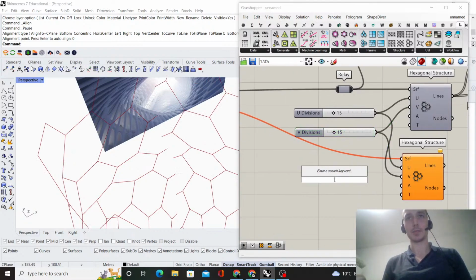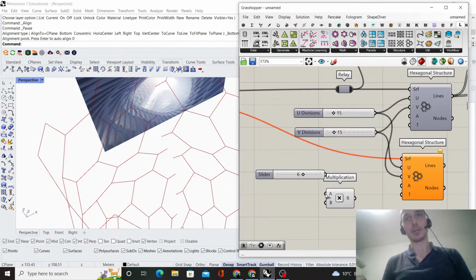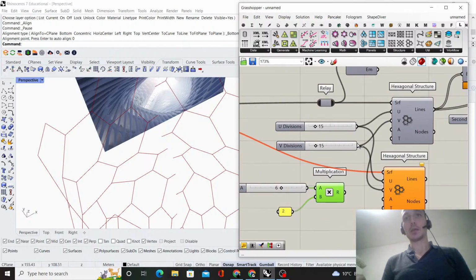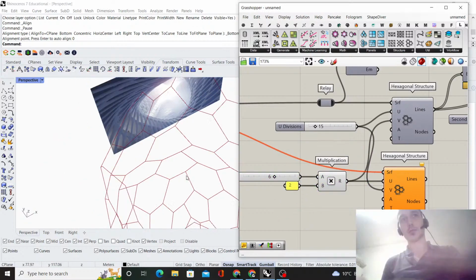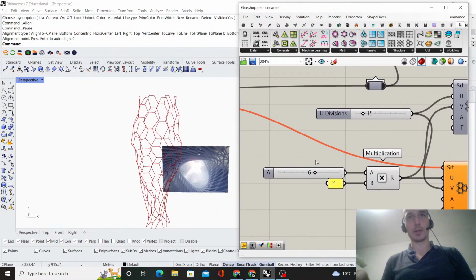So I might instead connect another slider multiplied by 2, and 2 will go as a panel because we don't need to change this number to anything else. Yeah, Shift Control to drag and reconnect those numbers. Yeah, there we go. Alright, actually this looks fine to me.